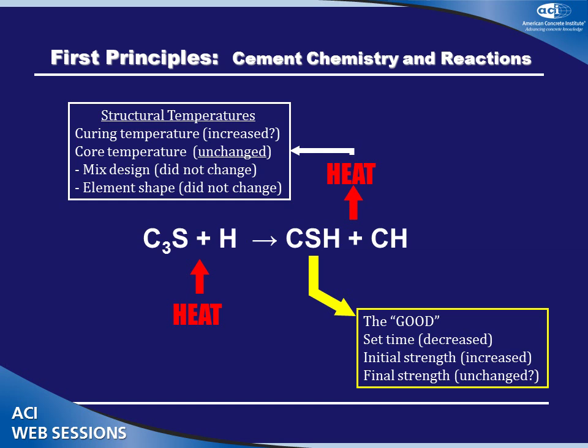My set time, of course we all know, goes down. I decrease my set time. My initial strength is increased. From a ready-mix standpoint, we always like to talk about we're cooking the concrete faster. We cook it faster, I'm going to get a burst of strength at the beginning.